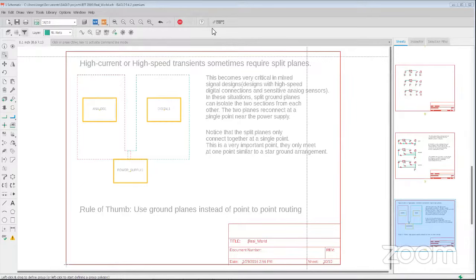In the case of the first stage, where you have the 12 volts being dropped down by a buck regulator, that's a switching regulator. Typically, a switching regulator nowadays is 100 kilohertz and up. A lot of people think that when you look at the data sheet of a linear regulator, which is what you have following it to drop it to 3.6 volts, the power supply rejection ratio is going to take care of any noise that comes prior.